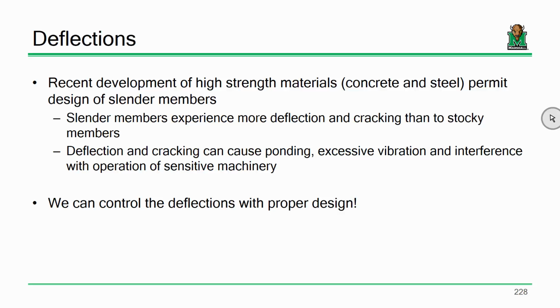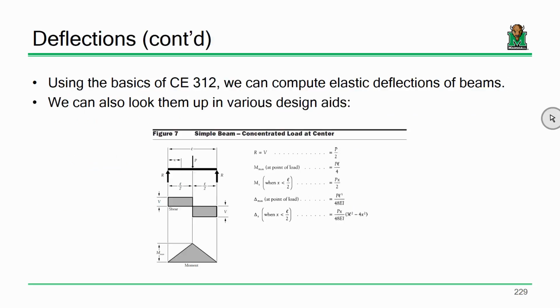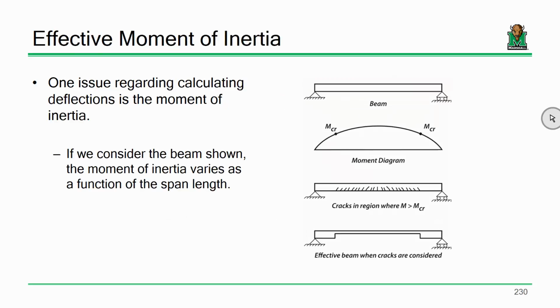And there are many times where in the design of a structure, the safety isn't even the issue. It's the deflections or the vibration issues or the serviceability or the just elastic stress limits. That happens quite a bit. So it's something that needs to be addressed. Now, in terms of just computing deflections, you all should know how to do that. We did that last semester. Direct integration, virtual work, conjugate beam method, we did that last semester. So you all should be good with that.